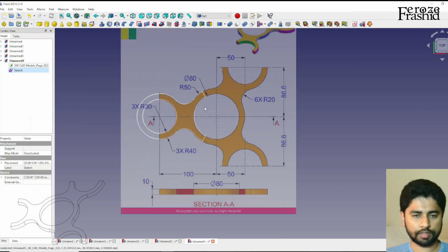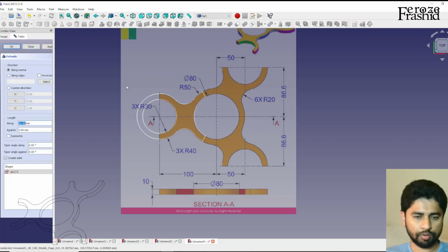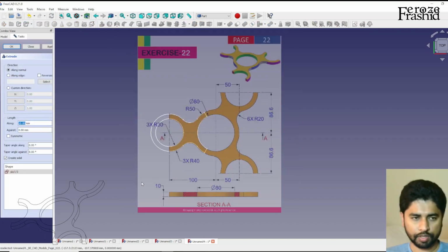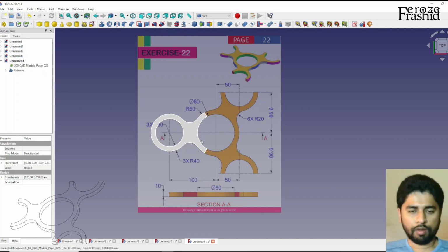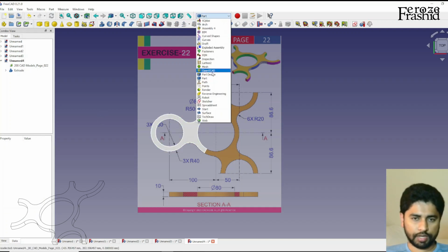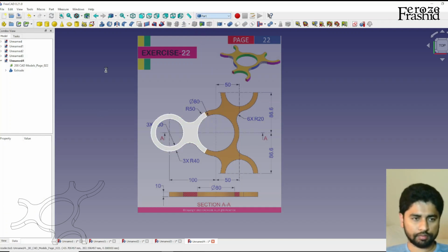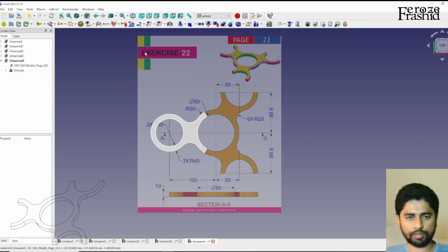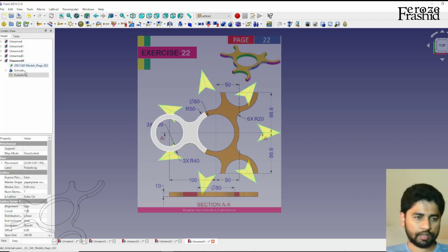Okay, and that's there. I want to rename that sketch as sketch 1/3 and pull that up by 10. What I want to do is replicate these 2 more times. So let's go ahead and pull in lattice. I know I should have gone with part design, but polar array, and their count would be 3.